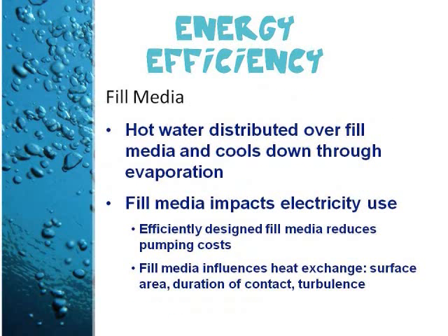We have already tackled the selection of cooling tower. Next, we will discuss the selection of fill media. In a cooling tower, hot water is distributed above fill media and is cooled down through evaporation as it flows down the tower and gets in contact with air. The fill media impacts energy consumption in two ways. Electricity is used for pumping above the fill and for fans that create the air draft.